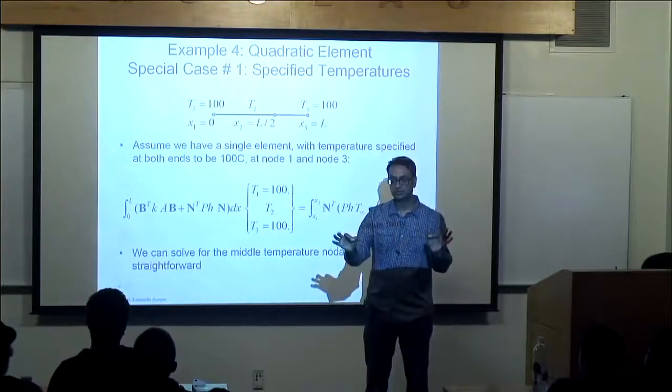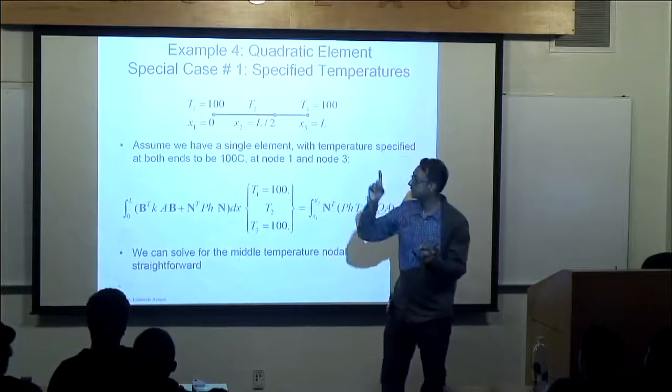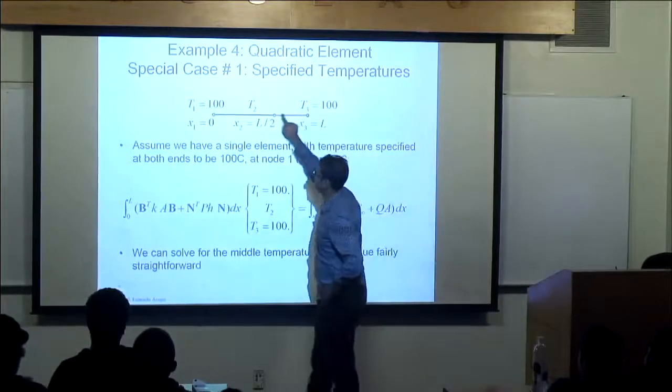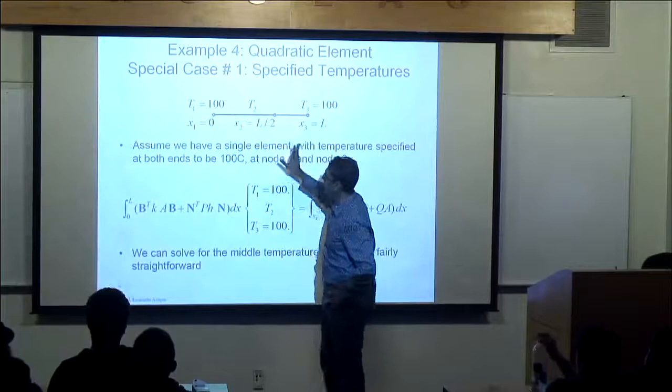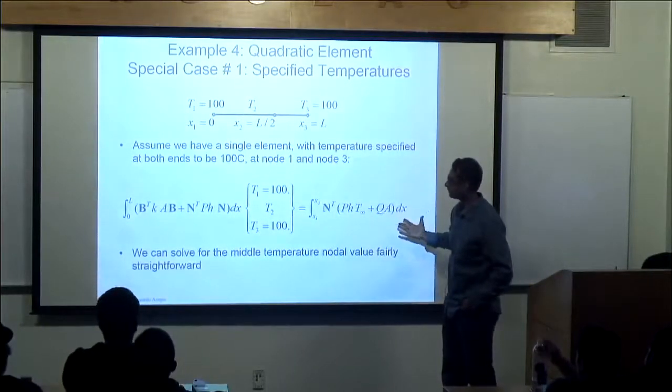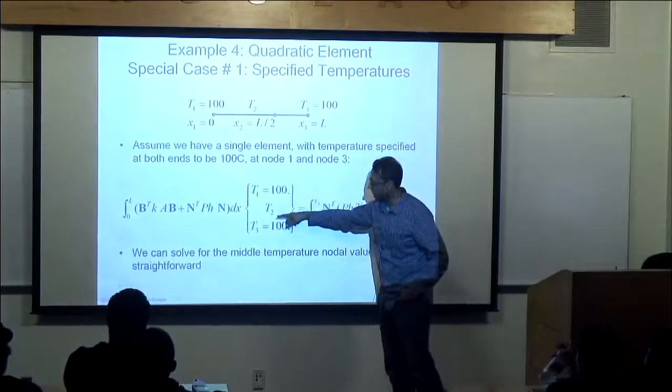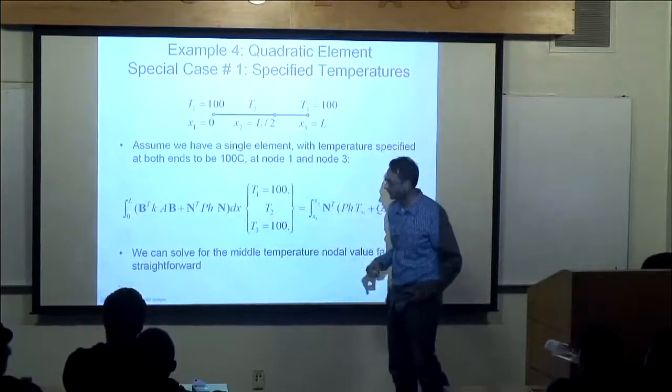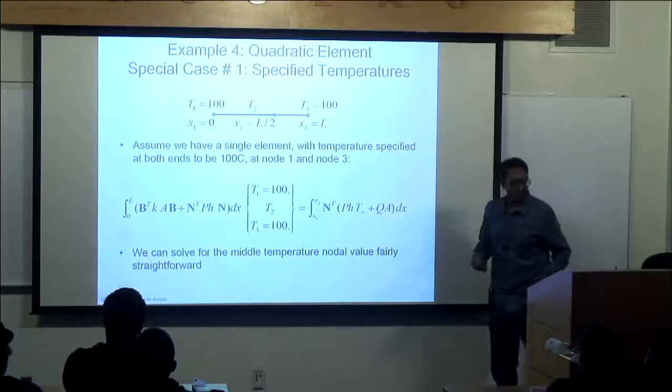So a single element, and in this case I'm specifying temperature here and here, but not here. Just a single element, so same process. Plug it in. This is 100, 100. One equation, solve for T2. That's a simple one.